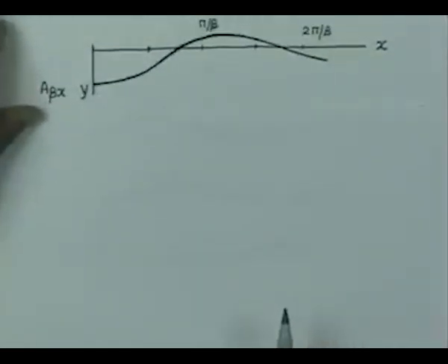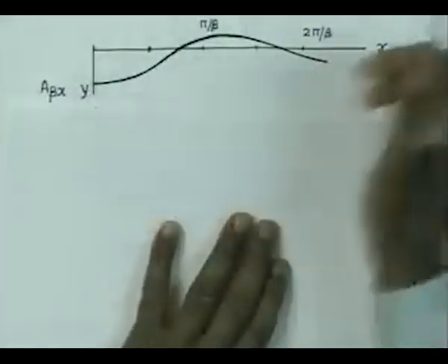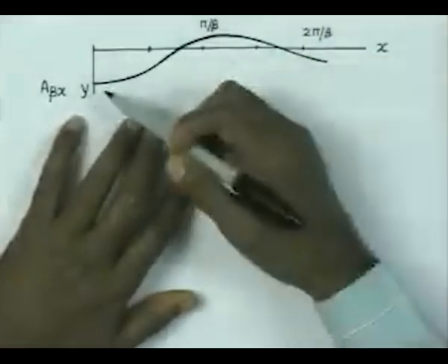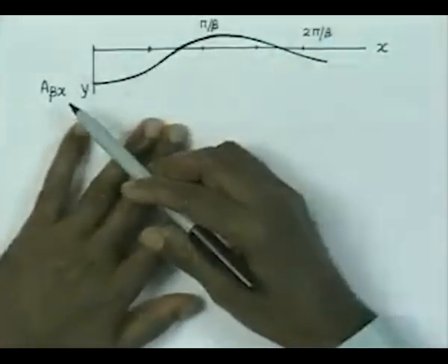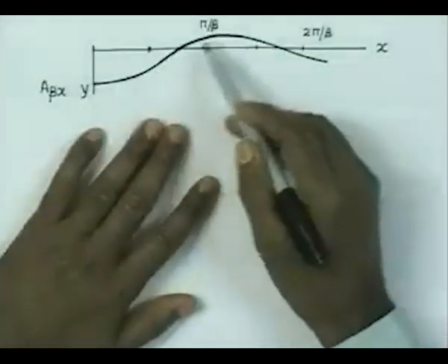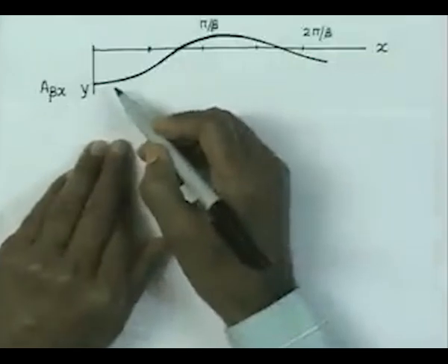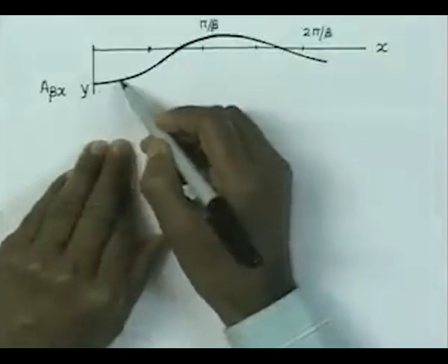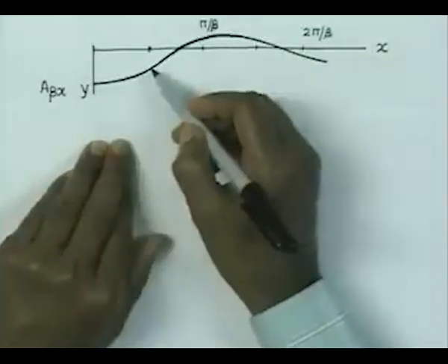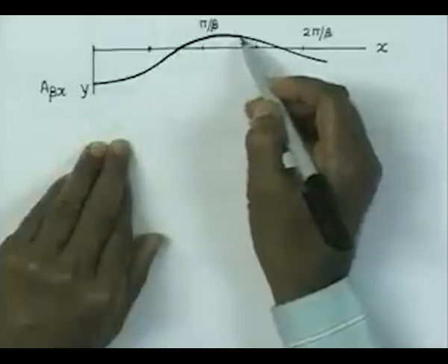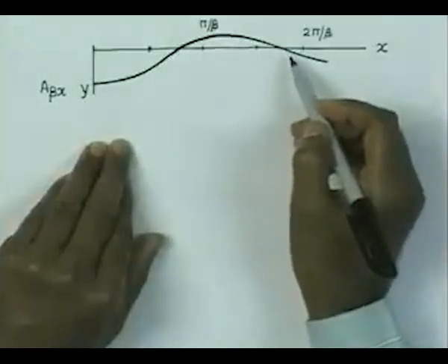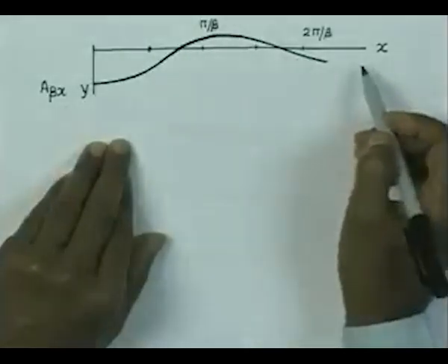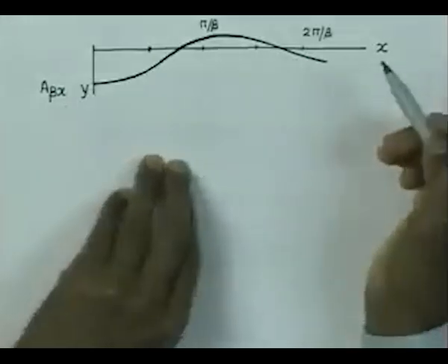So, if you consider the function y, which is directly related to A beta x, the plot of y, so also A beta x, is like this. You expect that there will be large deflection at the point of application of the load, it reduces and then it really tries to lift up the support and then again it goes on decreasing.